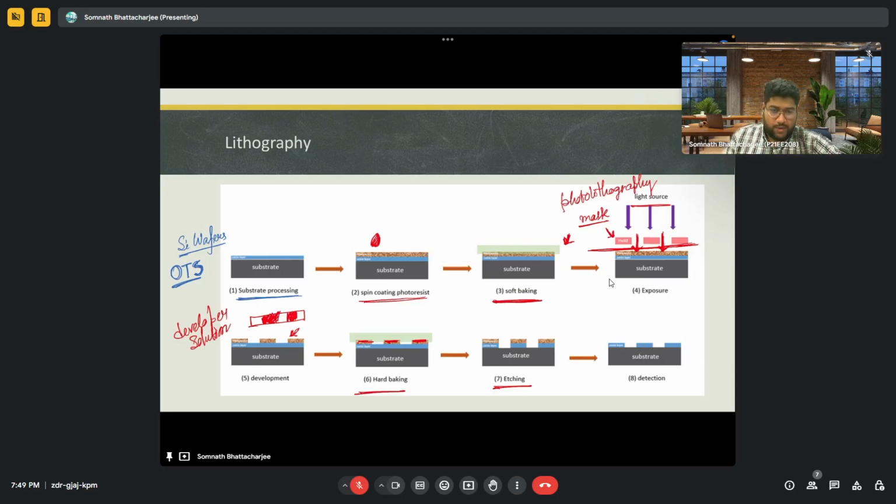And then what happens is that we just etch away this layer. It is the blue layer here. So these parts are etched away, and where there is protection, these parts get hardened more and more. After that, we'll dissolve the PR away, and this structure will be made on top of your, let's say, it can be an organic material, or it can be anything.